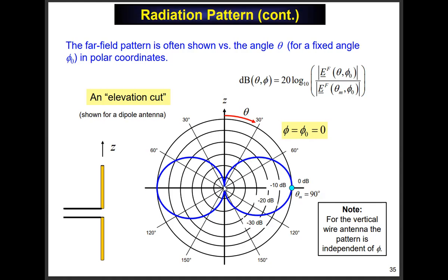But the disadvantage is you can never plot exactly where the pattern goes to 0, right? Okay, so the lowest you can get on this particular one is minus 60 dB. Anything lower than minus 60 dB got sucked into the center of the chart, right? And can't be shown. Okay, but that's a small price to pay. Antenna engineers usually like to plot this way. Okay. All right, does that make sense? You'll have to do one in the homework. So does that make sense?